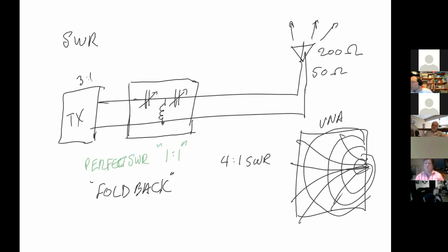Typically that actually puts out its own signal, so you wouldn't use it with your transmitter. You would remove your transmitter if using a VNA or an antenna analyzer, and it would put signals of different frequencies into the system, and give you a plot of what the system looks like at different frequencies. This is actually known as a Smith chart. This is on your extra class exam.